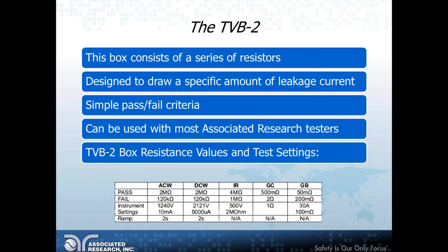But before that, this box consists of a series of resistors which are designed to draw a specific amount of leakage current. It allows the user to test with a simple pass-fail criteria and can be used with most Associated Research testers. Here's a table laying out resistance values and test settings for this. A simple and yet effective procedure can be set up, which can be run on a daily basis using this box.